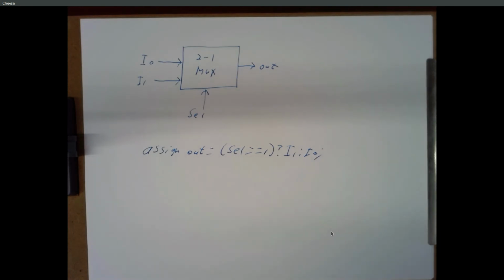There's also state machine specific tools available where you can do something like just draw a state diagram and it'll build a machine for you. It'll even neaten up your drawing for you if you like. You can say make it pretty and it'll put everything where it should so the arrows aren't crossing too much and so on. And there's a checkbox for full encoding, there's a checkbox for one-hot encoding, there's a selection box for what kind of flip-flops do you want to use and so on and so forth.